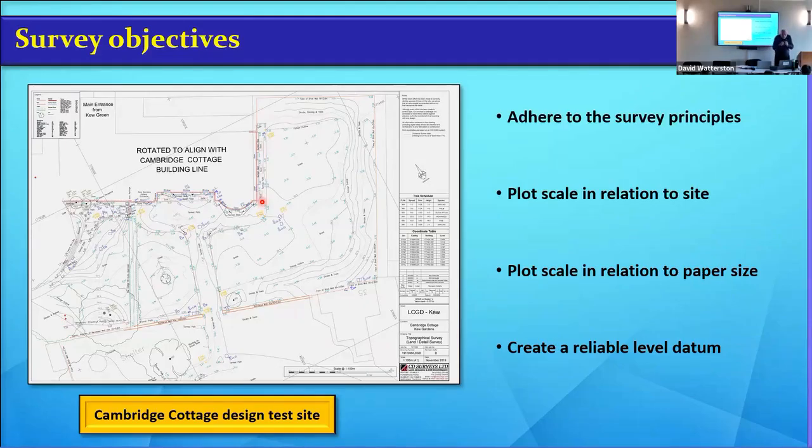What he'd done is he'd zoomed into our survey, and lo and behold, there were 3 little crosses in the corner. But you would never see it when you were right outside. It's only when you zoomed right in, because this little area of crosses looked thicker than somewhere else. So he zoomed in, 3 different crosses, and they were 3 mil different. He says, which one do I use? Well, to be honest, I didn't want to say you're taking the mick. But what I did say was, at the plot scale, we're allowed 30 mil, 50 mil, 150 mil. You're asking about 3 or 4 mil.